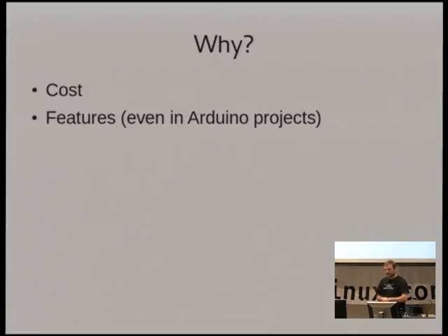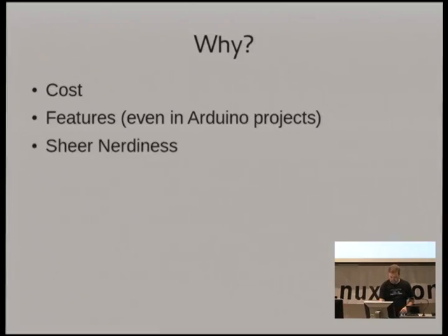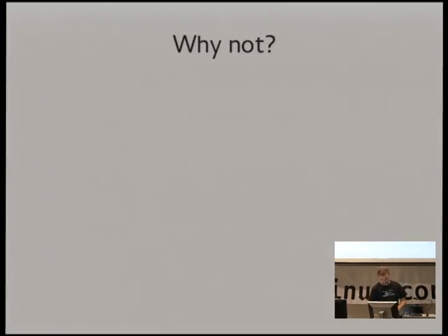The other thing is that there are a number of limitations of using Arduino, like only being able to have interrupts on a couple of pins, or only being able to do PWM on some pins. And sometimes that's just really, really irritating. It turns out you're not actually limited by the hardware to doing that. It just happens to be easier to do it the way that Arduino has done it in the hardware. There might be other reasons too.